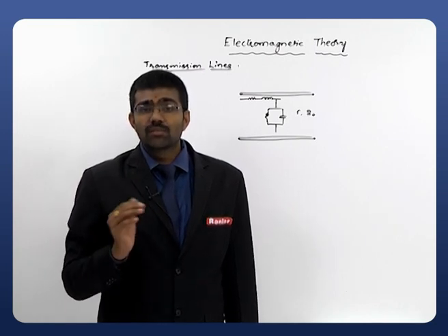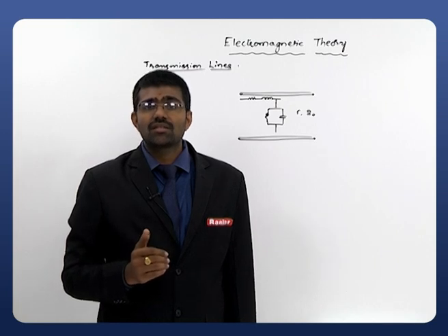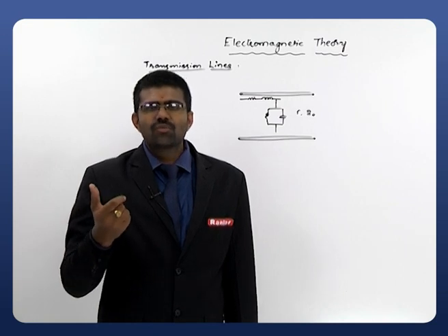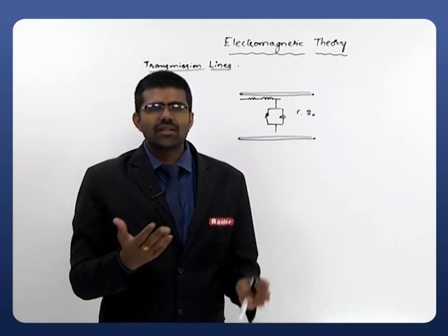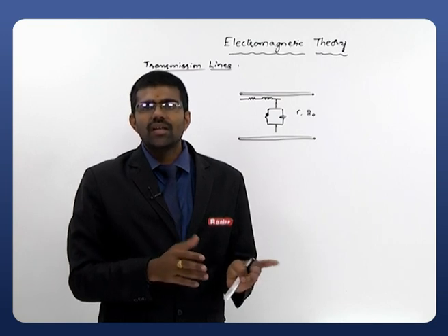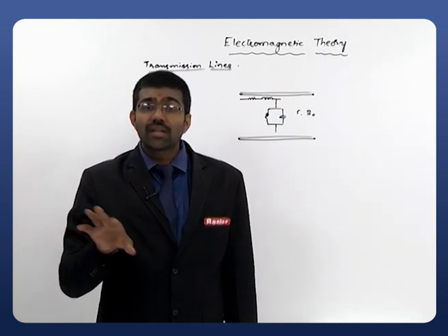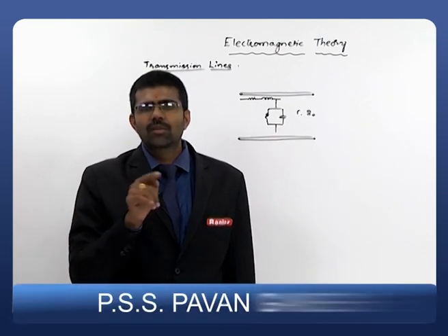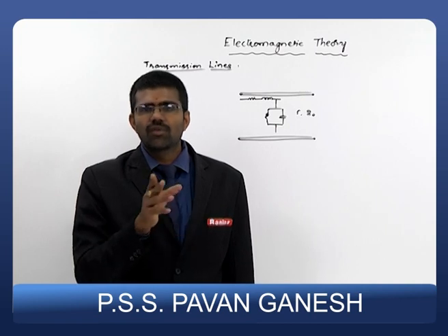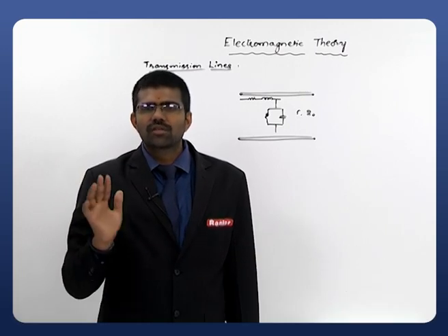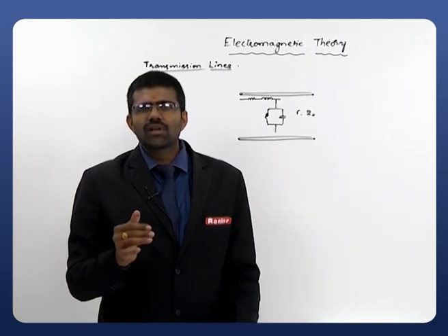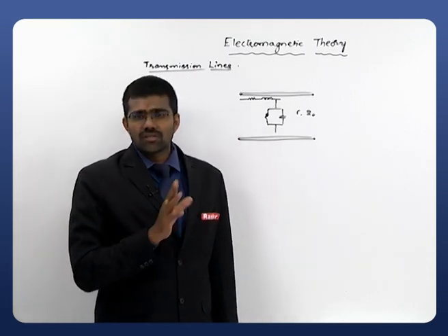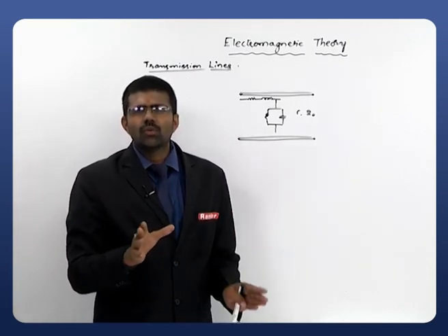Similarly, we have one more type of line that is called a distortionless line. Distortion is a parameter which is directly related to the frequency. So, whenever we are observing a distortionless line, the attenuation factor is independent of the frequency. It is not at all directly proportional to the frequency. And the propagation constant gamma is a combination of alpha and beta, right. That beta is directly proportional to the frequency. So, with this simple concept we have a simple relation, R by L equals G by C, for our distortionless line. Now, let us leave all these parts.